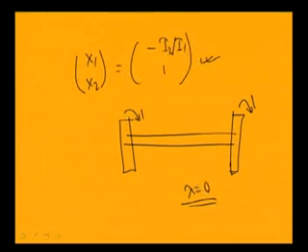when this is rotating in the clockwise direction, this will rotate in the anti-clockwise direction. So, for that reason you have this minus sign, and theta 1 by theta 2 will become the negative of I2 by I1. So, in this way you can find the mode shapes of the system by using the normal modes.